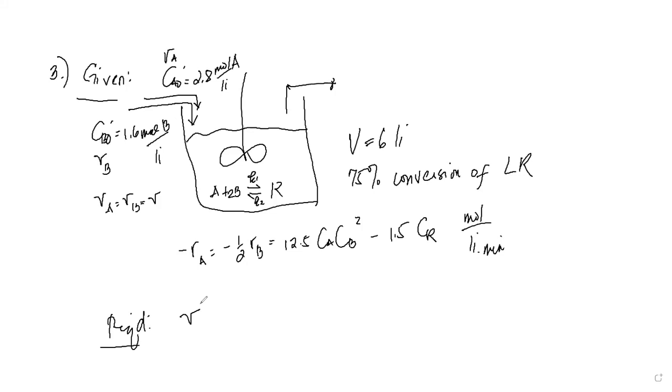Okay, so I will read the problem again. That way you can recheck if there's anything that is not reflected on the given information. So the liquid phase reaction, liquid phase meaning we have to write right away that your fractional change in the volume, or rather your expansion factor, is 0. So you have that particular reaction written here, and the rate equation is also written here.